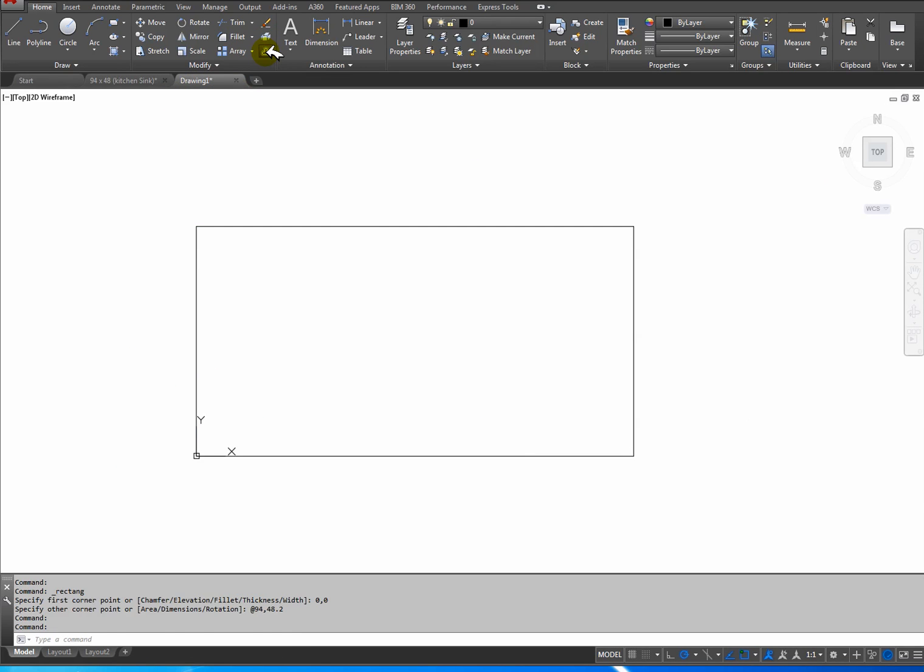So I'll say I want to offset, and if you look at the offset value here, it's 0, so I'll type 2.5, press enter, and my cursor changes into a small square, so that's a selecting cursor, and it says select object to offset. It says object without an S, so it means it's looking for one object.